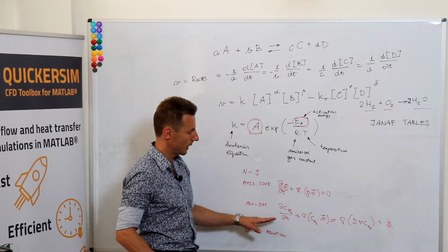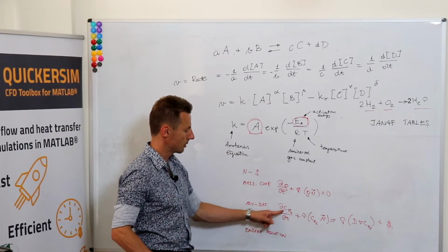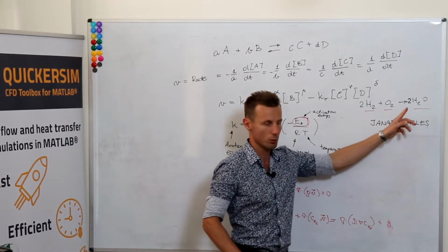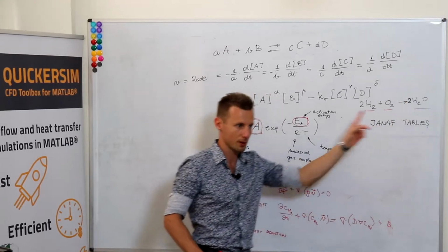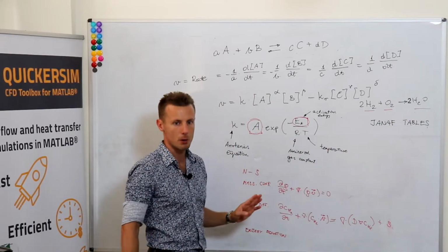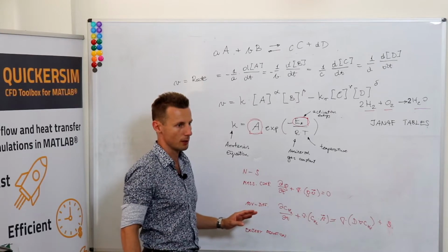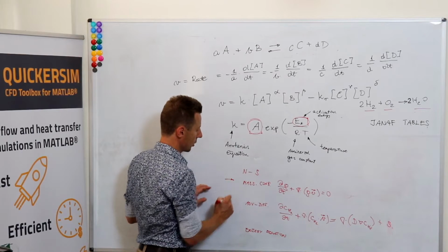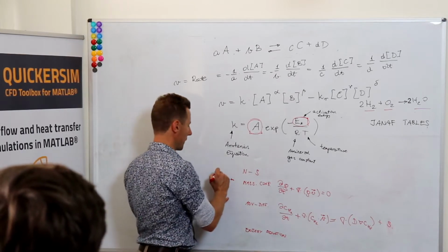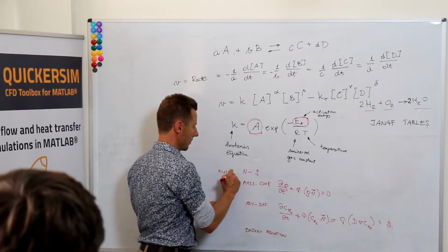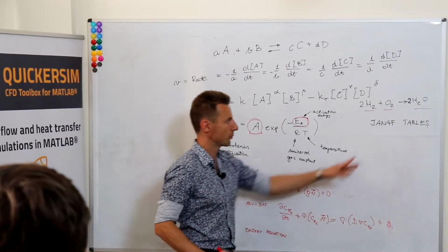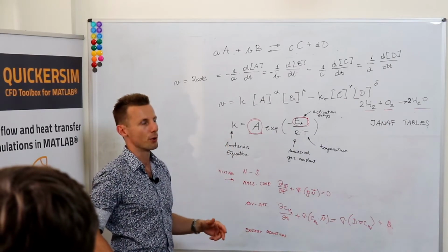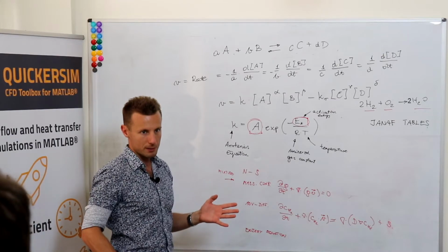What I want to underline is that you need to have such a transport equation for the H2, O2, maybe H2O component, but in most cases CFD codes are written in a way that you write one continuity equation for the whole mixture, and you're not writing equations for each element. You're writing these transport equations for n-1 elements.